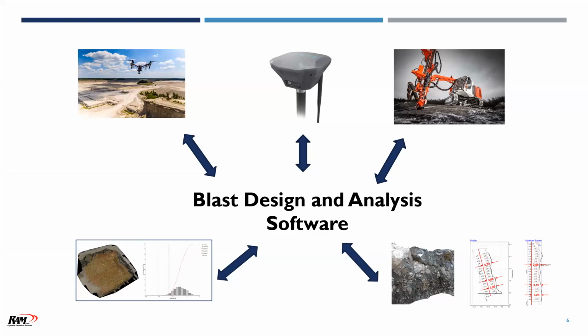Along with that is being able to also generate the profiles. And again, the minimum burden profile is what we need to be able to design that shot correctly and be able to optimize that blast. So it's important that we're able to capture that face accurately and then be able to generate the design according to the characteristics of that face.